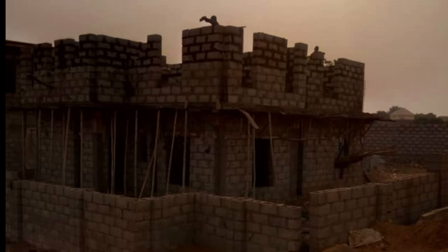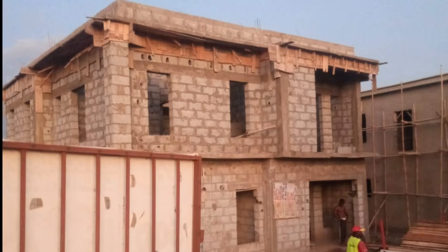Now, in this particular building, we had a roof slab over some areas like the balcony, staircase, and part of the bedrooms. So we also needed to repeat the process for the roof beam and slab. The bamboo props for the decking was removed after 3 weeks, that is 21 days, and used the materials for the roof level.